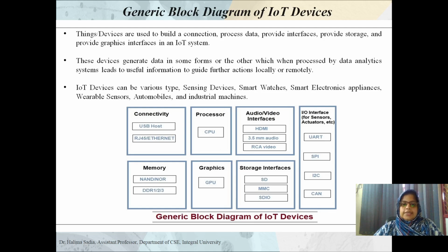Secure digital, SD is basically secure digital, is a flash non-volatile memory card format and is used for storage. Then we have SDIO. SDIO stands for input output functionality, and SD is only for storage memory. So the SDIO card is able to interrupt the host processor, while SD does not interrupt the host side. Host has to read or write to the SD card.